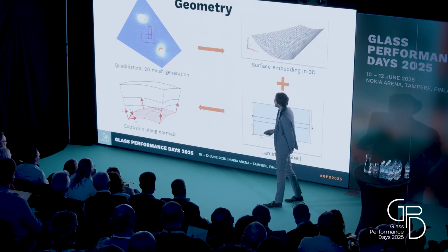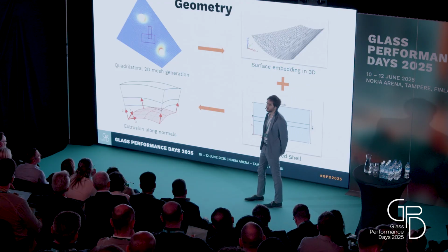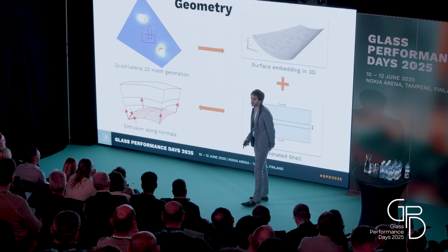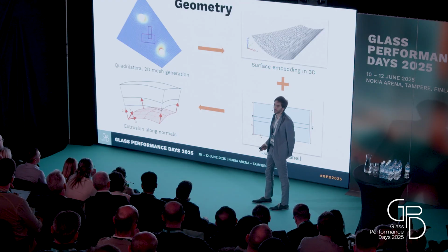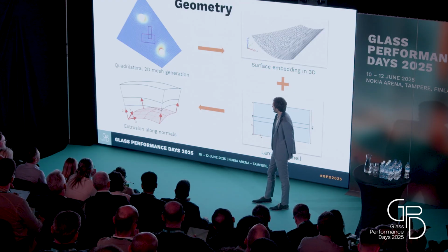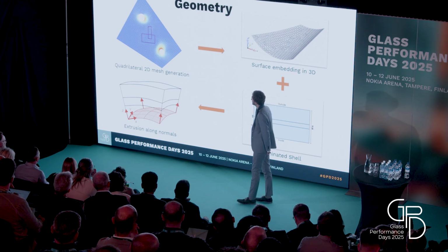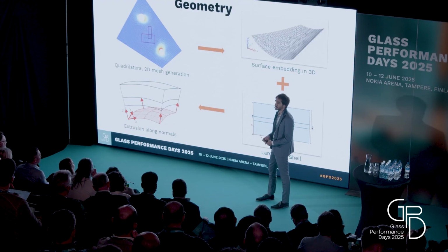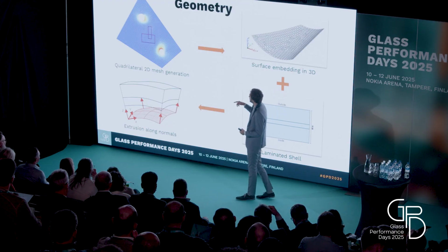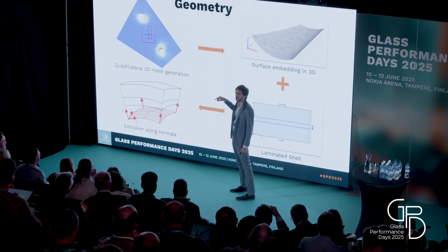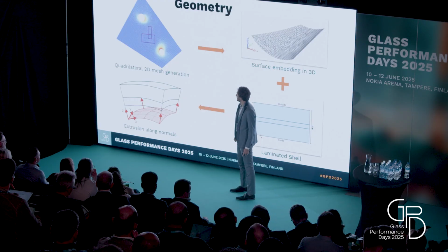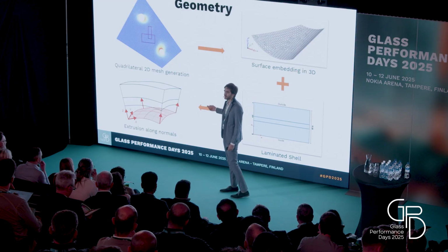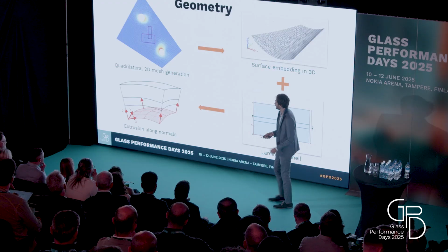For the mesh, because we usually need complex shapes with holes, with loaded areas, and we want a good quality mesh, we built our mesh solver from scratch. And the mesh is built by using a diffusion. We diffuse not a temperature, but the direction of the line on the boundaries of the surface. And with this diffusion, we can put all the points for the elements, which results in good quality quadrilateral elements.